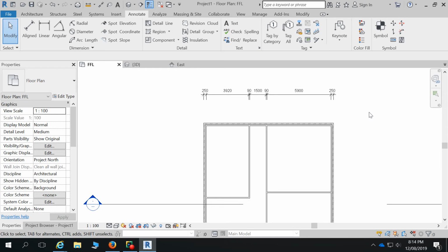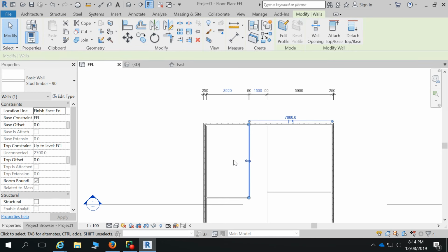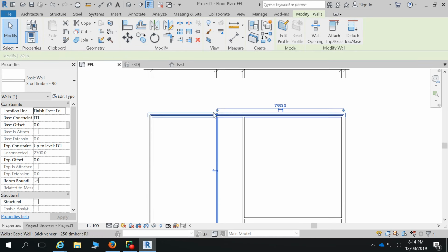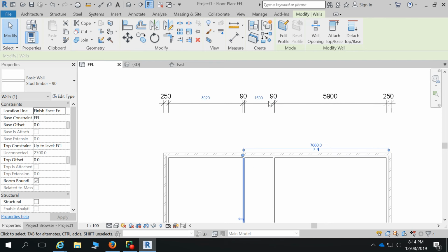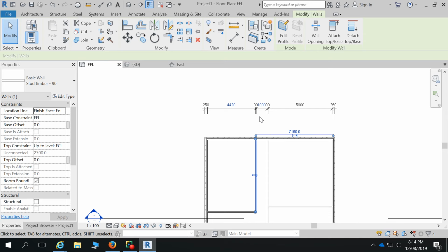So now if I said for my drawing again, that passageway that I changed to 1500, I want to change it back to 1200. You can see the temporary dimension that I moved is still referencing that area, but these permanent dimensions have also gone blue, which means I could type in here and change it in there. So it's quite a handy way to get your building changed quite quickly by putting some really quick dimensions around the building and using them to change some wall spacings.